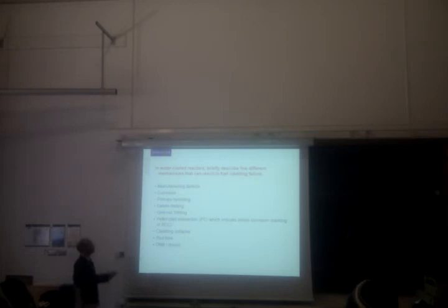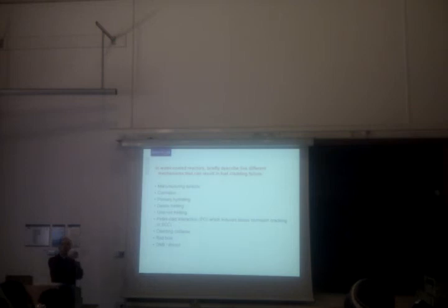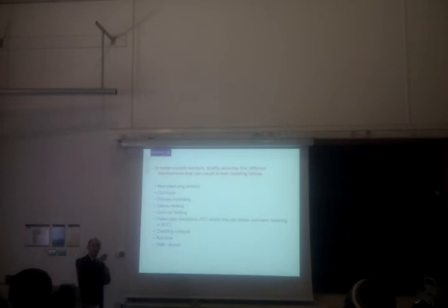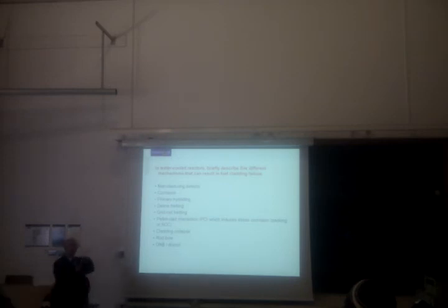The two types of fretting that we can get are debris fretting and grid to rod fretting. Remember that the rods are held in place by grids. They've got water flowing past them at a very high rate, and they can rattle about in the flow, and they fret against the side of the grids and wear, and eventually that can wear through.